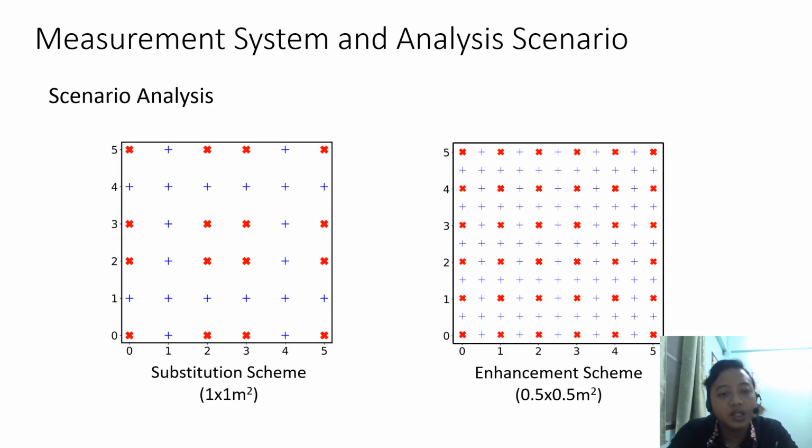We organized 2 main steps to examine the various spatial interpolations to synthesize RSSI to enhance the database. In the first step, we remove some RSSI values and replace them using interpolated data, as in the left-hand figure. The red cross represents the measured data retained for interpolation. Meanwhile, the blue plus sign denotes the data that is removed and replaced by interpolated data.